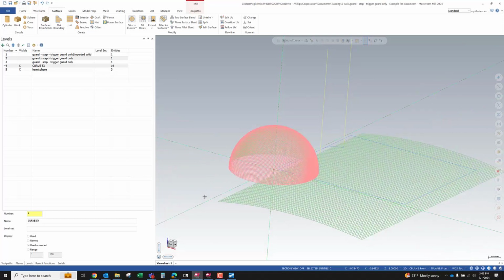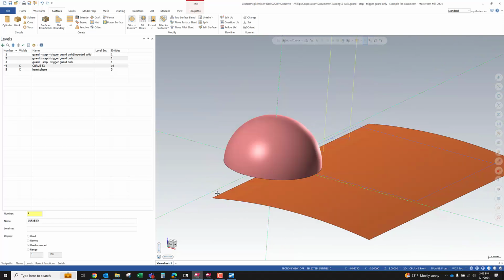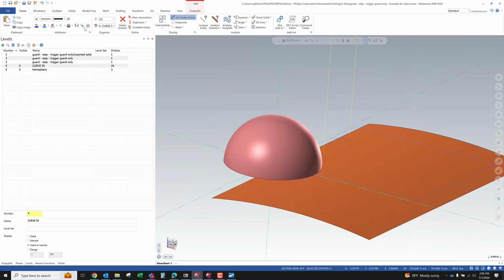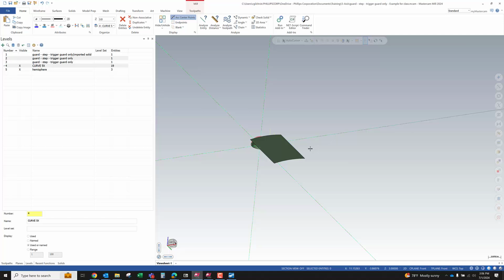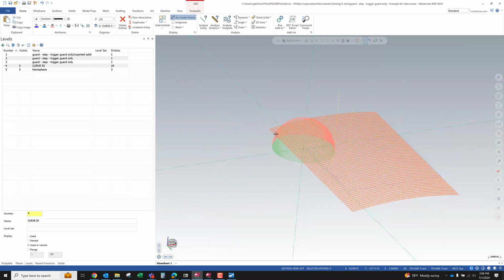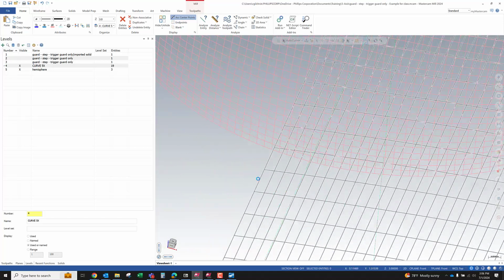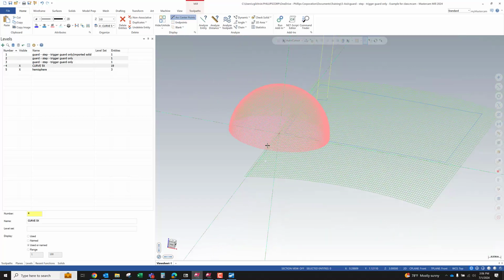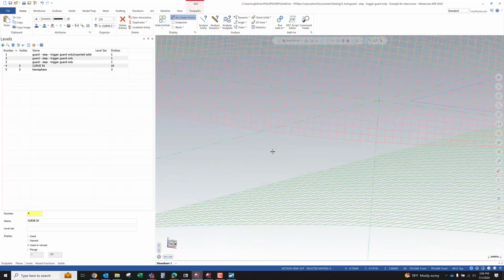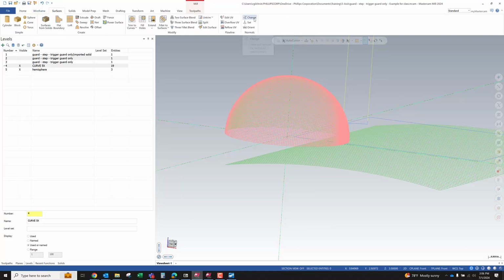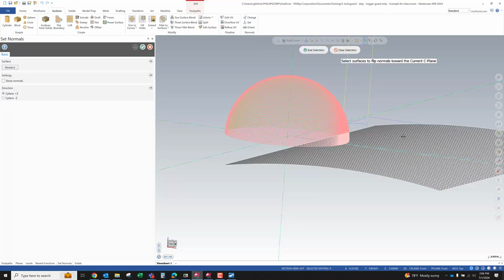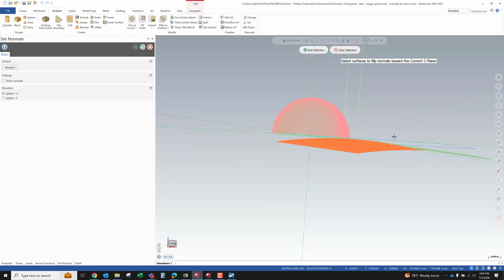What happens if you grab that speed menu and clear colors? Does it have the same problem, or does that rectify it? Now, it's not a zoom thing either. It's just plain old backwards. In unshaded, it's showing me a reverse normal. Because if I go to surfaces, set, it's not even giving me the arrow.